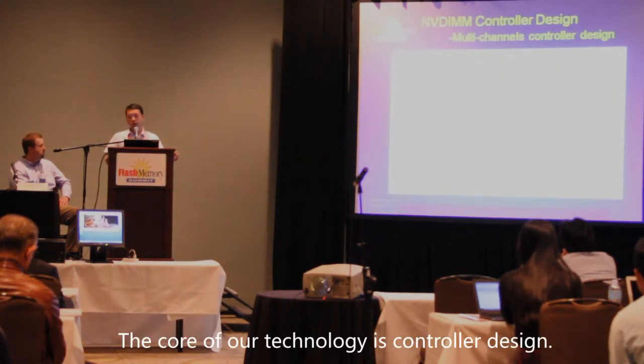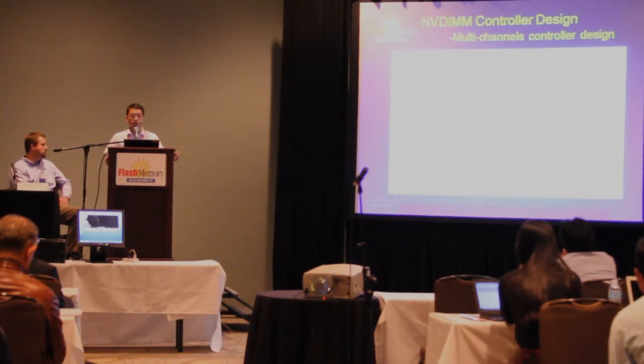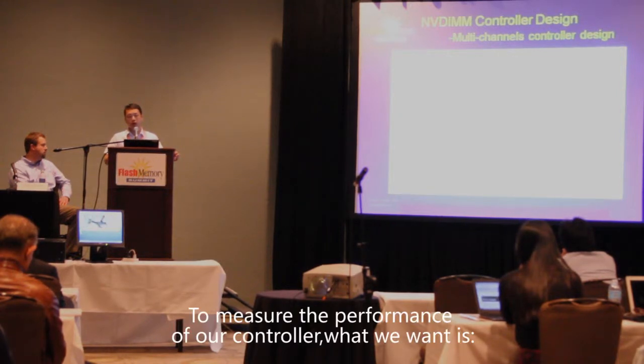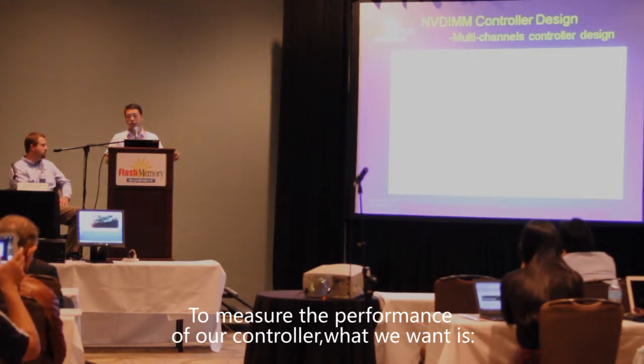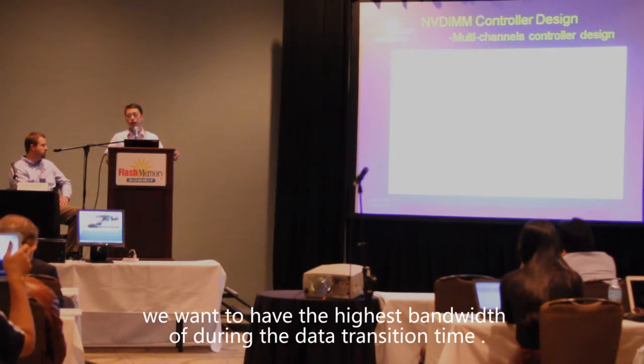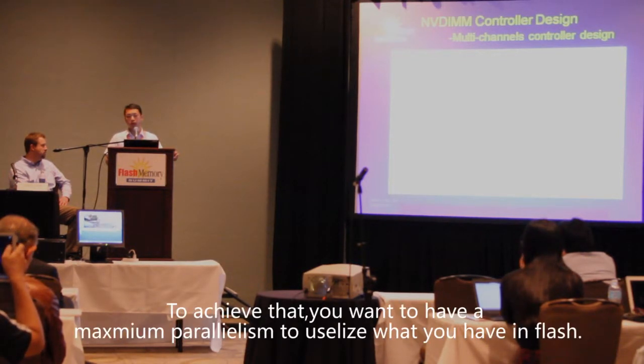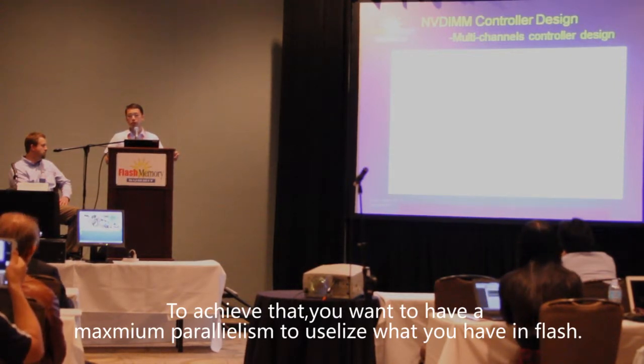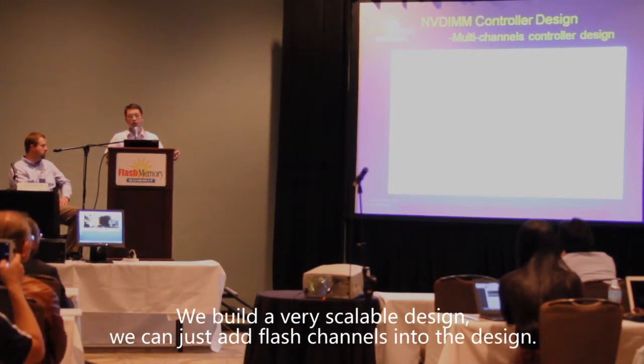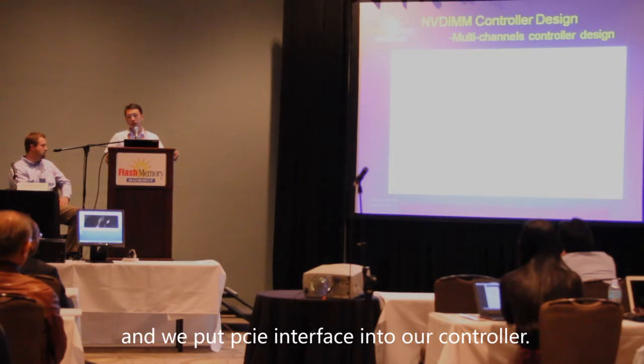The core of our technology is the controller design. To measure performance of the controller, what we want is to have the highest bandwidth during the data transition time. To achieve that, you want to have massive parallelism to utilize what you can have for flash. So basically, we built a very scalable design. We can just add flash channels into the design. And also we put a PCIe interface into our controller.